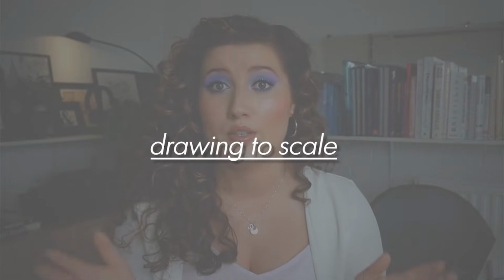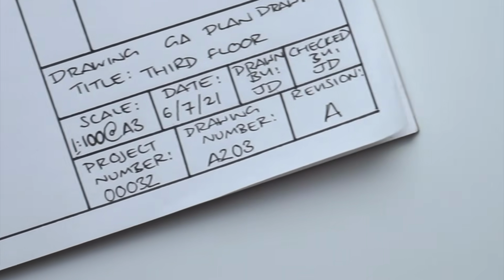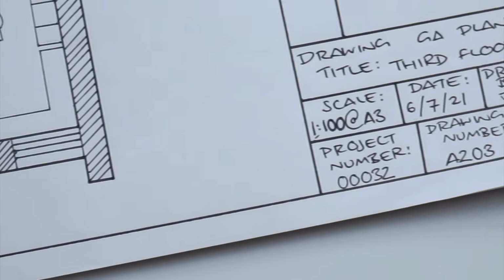I should have probably said beforehand that before you begin to draw, you need to decide what scale your drawing is going to be at. How are you going to fit a building onto a piece of paper to a precise scale? For this drawing, I'm going for a 1:100 scale on an A3 page.